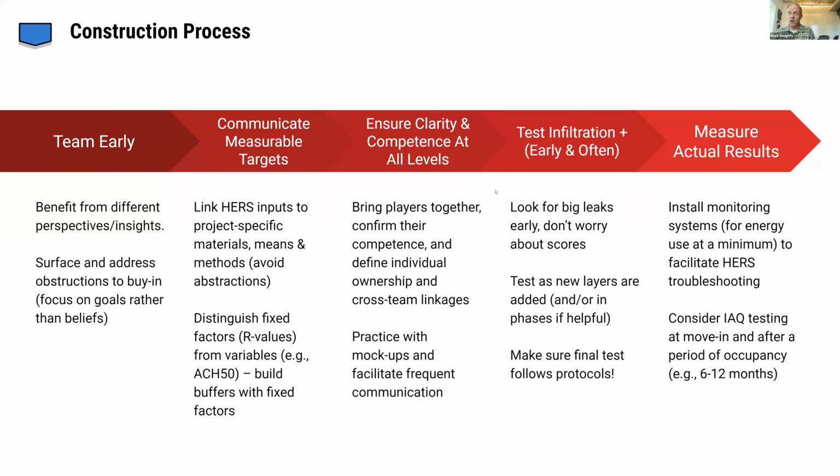HERS raters who have come to the site who didn't have the proper aperture for their blower door, or other things that they weren't prepared for because of the nature of the home. So just really making sure that there's good dialogue with the HERS rater. HERS raters that we've worked with know a lot, but they work in such a variety of homes that when they come to one of the homes we're working on, it's really helpful to have conversations with them about what they're experiencing and how they're going to work with the house that we've built.